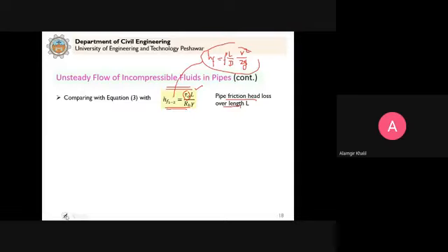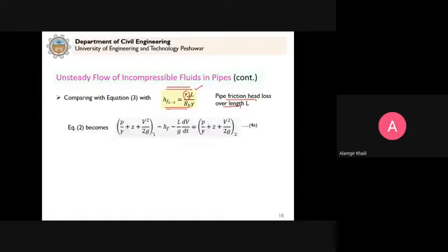Steady flow. Now the flow is unsteady, so the acceleration terms come into the analysis. That's why we can write down the three forms of energy at section 1 minus hf is equal to this. Ignore this term. If I ignore this term, what is this equation? Steady flow. This is what we developed in chapter 8, treating it as steady flow. The chapter name was Steady Incompressible Flow in Pressure Conduits. Now we are studying unsteady flow, so this unsteadiness comes by this term.